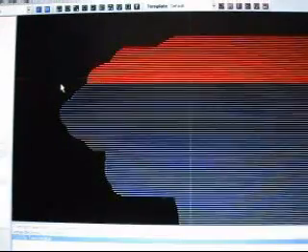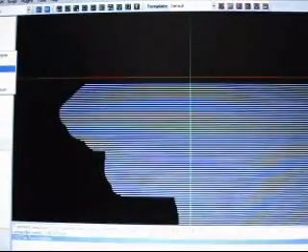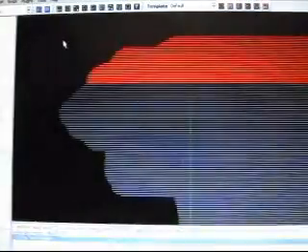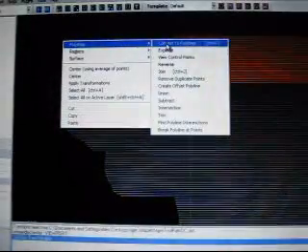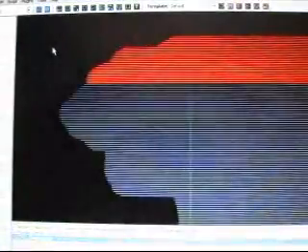You know, it takes some time to do this, so just going to cut that, show my layer, paste it there, polylines, convert to polylines, polylines, join. See, the smaller section I choose, the quicker the processing time is.